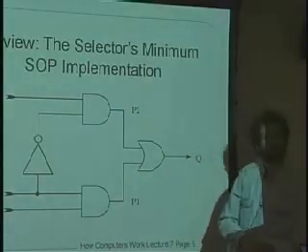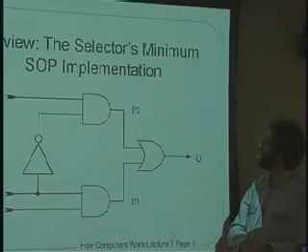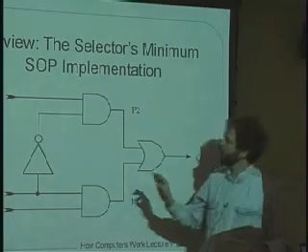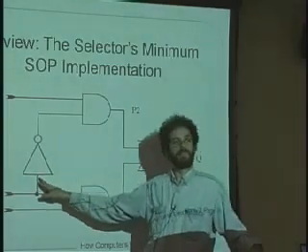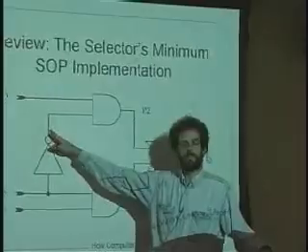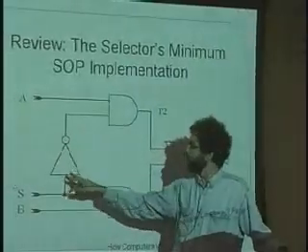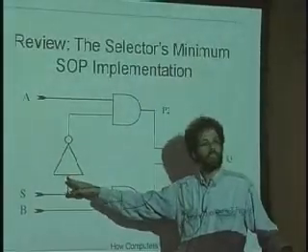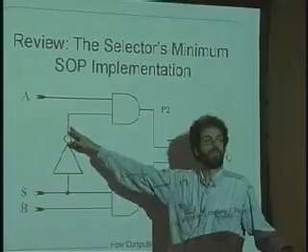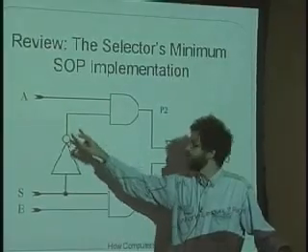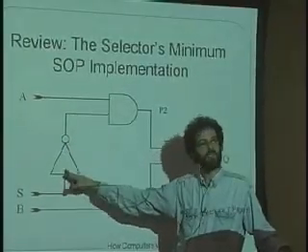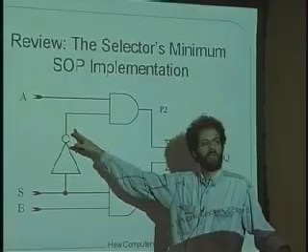Yeah, I can see now how the AND gate works, but how does the inverter work? Because it either takes away charge or it adds charge, right? Well, not exactly. This is the input side of the inverter, and this is the output side of the inverter here. So when there's a logic 0 here, a short time afterwards, a logic 1 is created over here. And when there's a logic 1 over here, a short time later, a logic 0 is created over here.